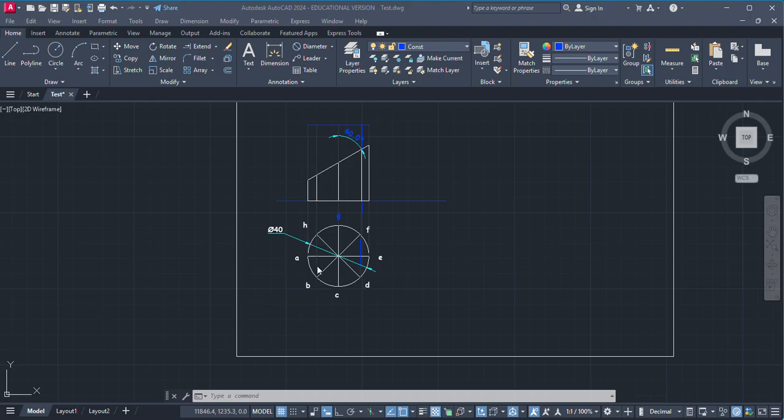And we have divided the circle into 8 equal parts. After opening up the circle into a straight surface, you will get a rectangle. Similarly, the complete circle will give a big lateral surface. After opening it up from this point, it will give a big rectangle whose length is 125.6 mm and height is 50 mm.